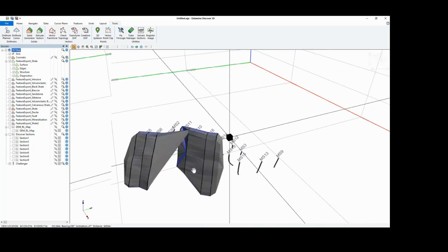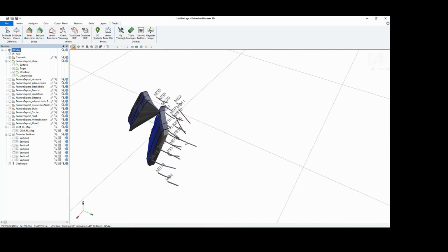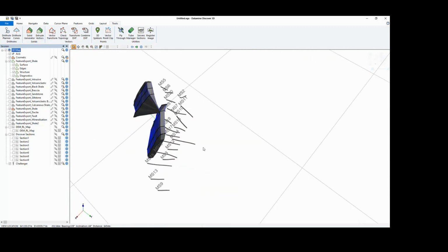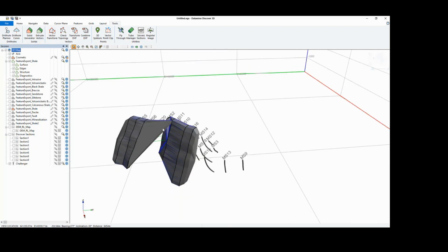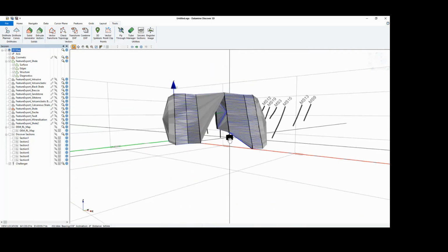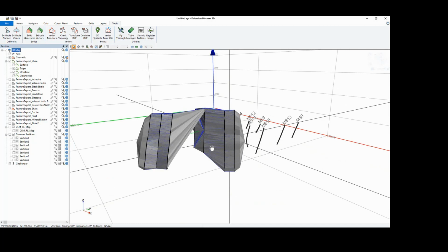And as you can see here, it's because it's sort of detected that there's two bodies there, and it's tried to join them up, which is incorrect, but you can actually use tie lines to join those together. So then you could have those two bodies joined, or there's options in there which allows you to have two bodies created instead. So yeah, so that's the solid feature.